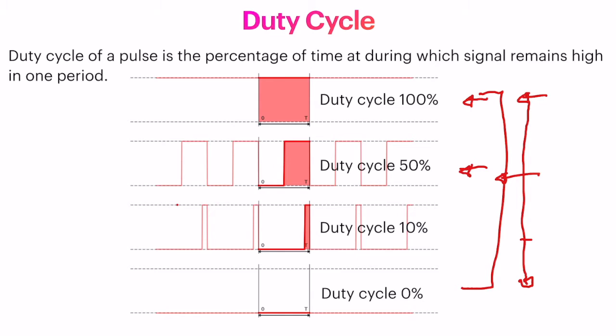So this is the basic idea of how we control the digital signal, and we will see it done through an LED, whether it really brightens or reduces the brightness by changing the duty cycle. So that is what we are going to do through an Arduino. One can use analog systems such as the IC555 and similar systems to change the duty cycle of a square wave. On the other hand, this can be done more easily and elegantly using microcontrollers. We use a microcontroller to send a signal to the LED in this case, or to any digital system for controlling.